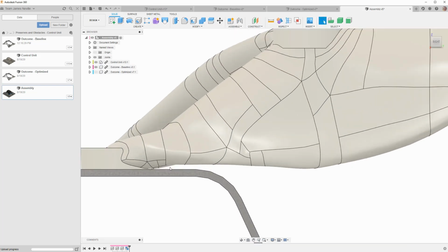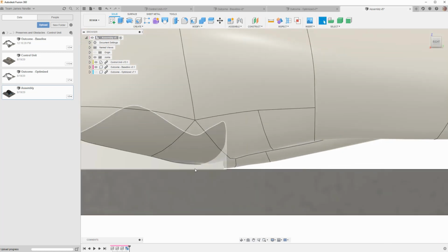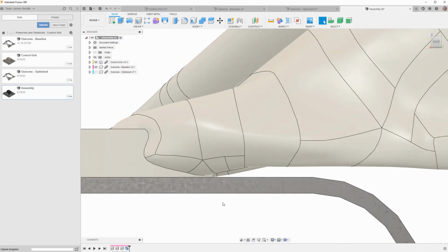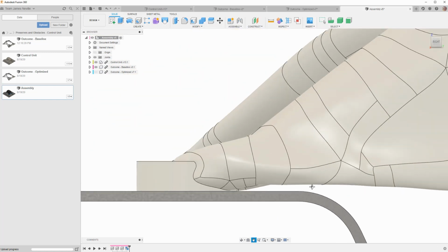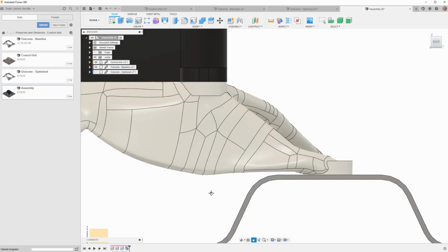You can definitely tell the form body gets really close to that sheet metal part, which I don't particularly like. You can see that there's no room to even add stress relief. And sometimes this will actually just be flat with that. So you get these little tiny edges that are just tough to work with afterwards. Can you work with them? Of course, but it's just easier to handle them in pre-processing than in post-processing.